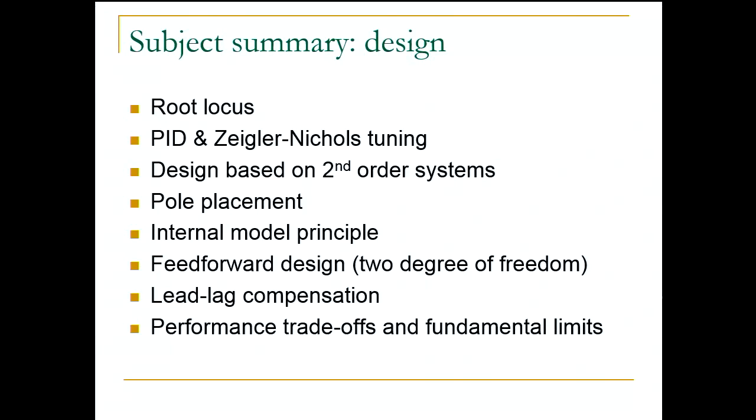So what we learned was that in order to achieve tracking of such reference signals or rejection of such disturbances that we can model in this way, you need to include the model of such a reference or disturbance within the controller transfer function and then stabilize the system. So if you stabilize the system and the controller has that model of the disturbance internally in its transfer function, then you can track those references and reject those disturbances, right?